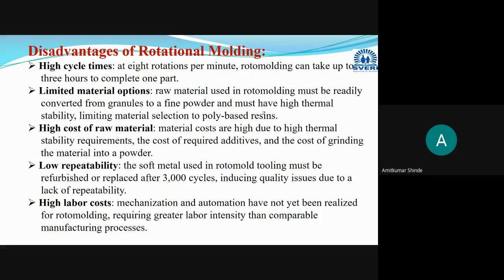That's why it is limited to some specific polymers only, or specific plastic materials only, because here we must be able to convert that polymer or plastic material into the fine powder, and some thermal stability is also required, as we are heating it here, and we are rotating it also.